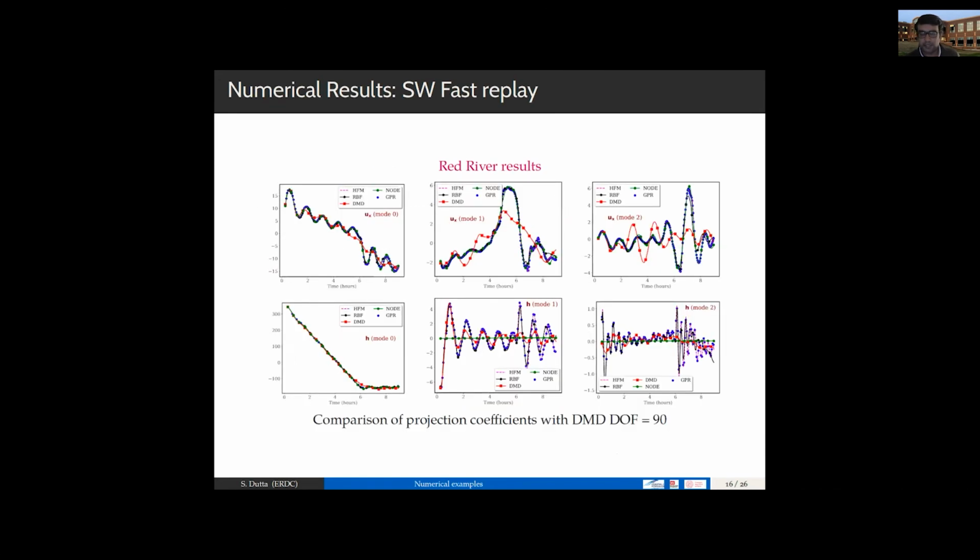So now, again, looking at the expansion coefficients, this is with the coarser degrees of freedom for DMD. You can see that, again, the representation error is absolutely terrible, even in the most dominant modes. And this also ties to the fact that DMD doesn't necessarily use the energetic criteria in selection of modes. So the frequencies that are being selected inside these 30 degrees of freedom may not correspond directly to the most energetic modes, so it's not necessarily representing this particular mode well.